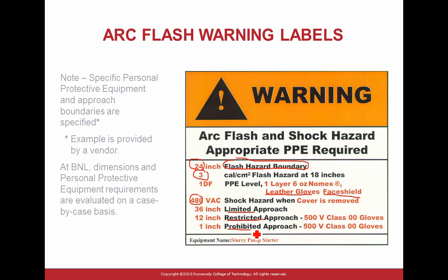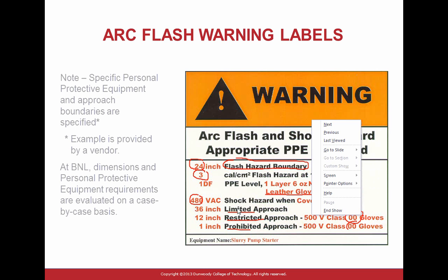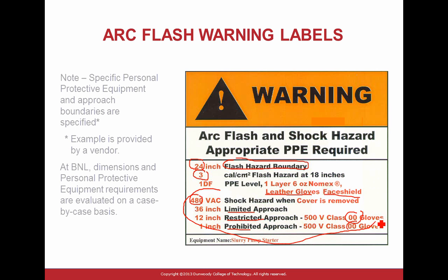And you stick it onto the system. And here's the rating of the gloves that you're supposed to use. So that will be 0, this type of gloves if you're working on it. So remember, guys, this part is to protect you from the shock. And this part here is to protect you from the arc. So there are 2 parts, 1 shock, 1 arc. Any comments, any questions? This is required on every industrial control panel.